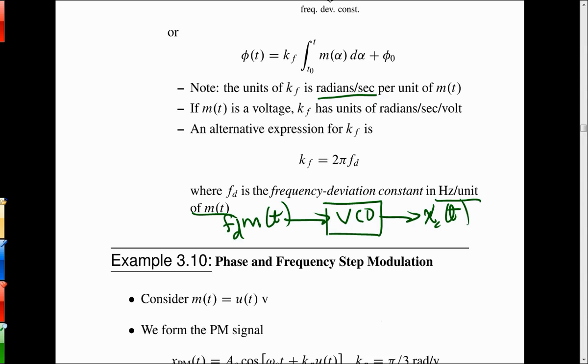Well, if you build an oscillator that has an LC tank circuit in it, you know, an inductor and capacitor, all you have to do to make it a VCO is slap a varactor diode or some diode that you can change the bias on to change the capacitance, and then the tank circuit's center frequency changes, and you just decouple that from the RF so you can feed a signal in, and then you've got a voltage-controlled oscillator.